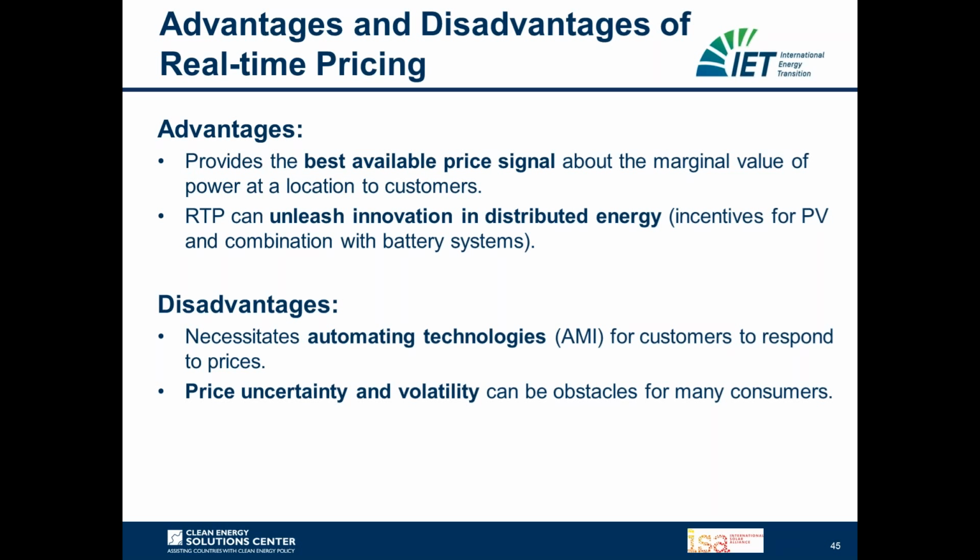However, please keep in mind that with an increasing share of solar PV, once you get to 5, 10, 15%, wholesale electricity market prices will be depleted during these periods of the day, which is called the merit order effect. We're going to have one session on the merit order effect in this training. So once you reach higher shares of solar PV, real-time pricing can also be a disincentive for installing solar PV, because wholesale market prices will go down, and this will be passed on directly to the final consumer, to the retail electricity price. This is always a changing picture.